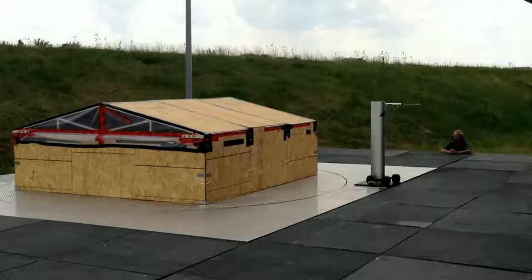Initial displacement of the windward roof-to-wall connections can be classified as a serviceability failure, allowing for the formation of a gap along the windward eave and allowing potential wind-driven rain to penetrate the building envelope. Full withdrawal of a single roof-to-wall connection is a structural failure, affecting the load distribution between the roof-to-wall connections and accelerating the failure process by shedding load attributed to the failed roof-to-wall connections towards adjacent roof-to-wall connections.